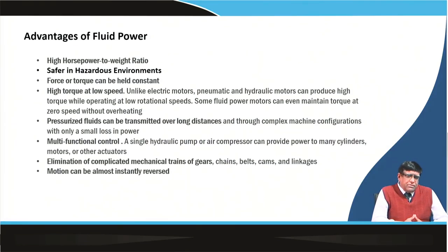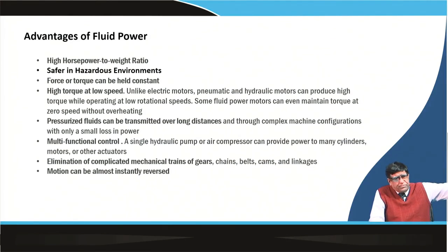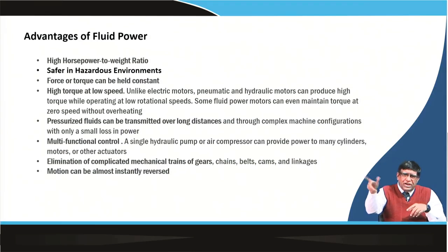Pressurized fluids can be transmitted over a long distance, because if you make a longer pipeline, you can get the work done at the other point. Then there can be multifunctional control, as you have seen that from one hydraulic pump in a drilling jumbo, 4 drills can be operated with the same hydraulic motor.